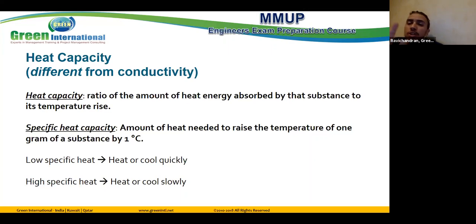Both actually are highly conductive, whichever one is higher than the other. The response of heat transfer is controlled by specific heat. So go to the table, check the part referring to specific heat, and see which has low specific heat. That one heats or cools quickly.